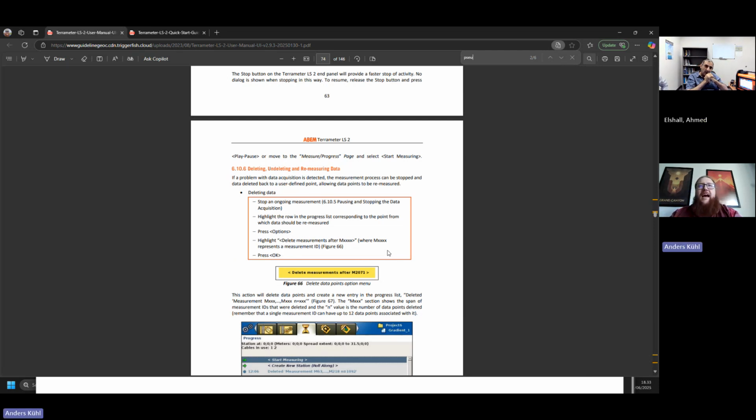Yes, there are two ways to do that. Way number one is, before you move the instrument, you create a new task. Then in that task you select a Wenner setup, and then just measure the Wenner. The other one is that you can make a custom protocol where you add the Wenner ones in and then measure it all at once. But usually people want to look at them separately.